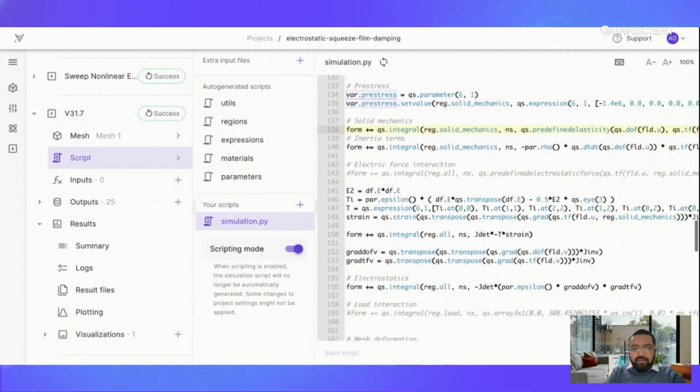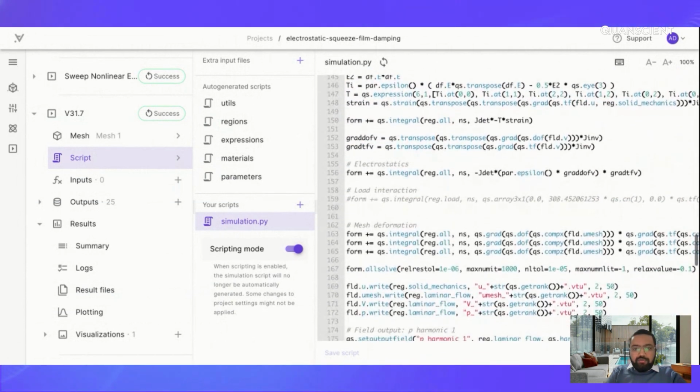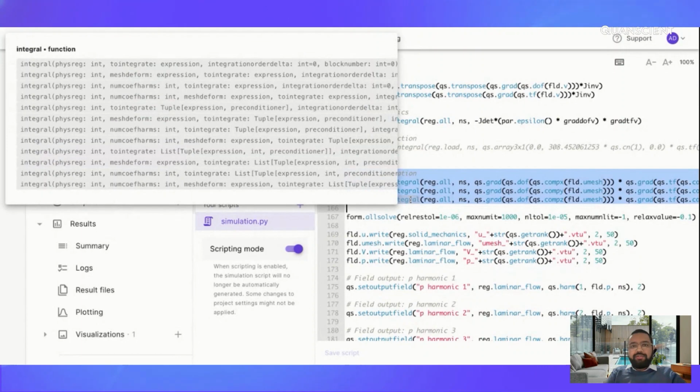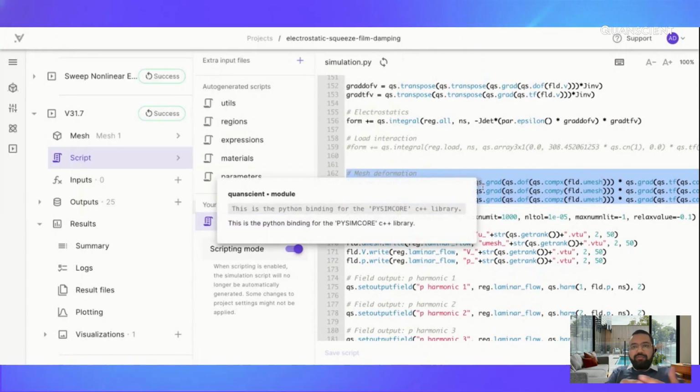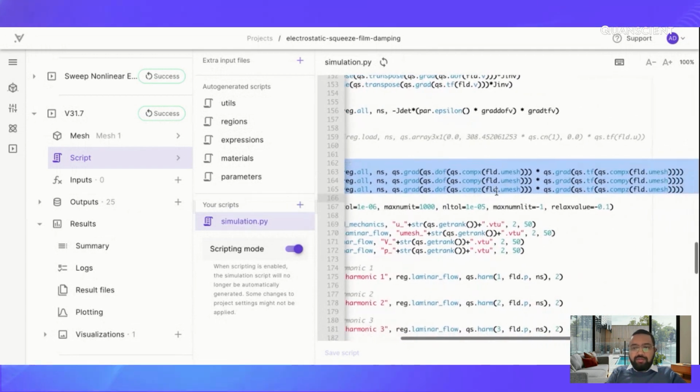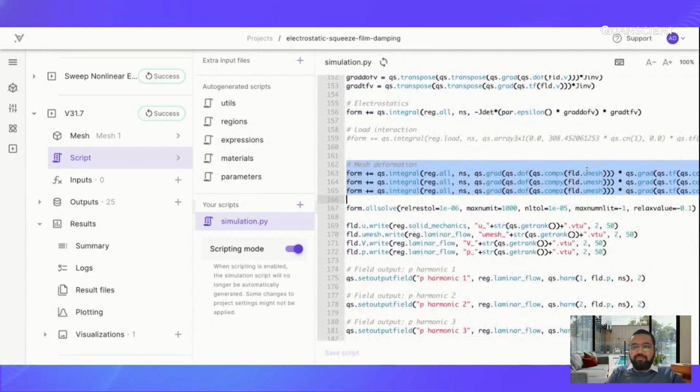We just define two lines of code, and we have to include the pre-stress as the argument, and that's it. And once we have done all of that, the last thing, which is auto generated, is to tackle the deformation of the mesh itself. As we deform the mesh, the nodes are redistributed smoothly using a Laplace solve for the mesh deformation field. So this wasn't added by me, this was auto generated. And once that is done, we are ready to solve.